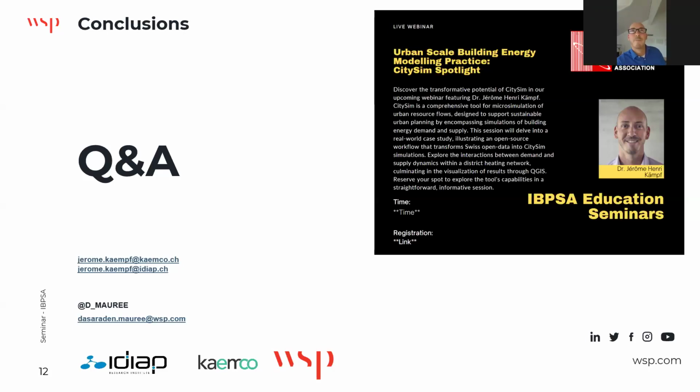Basically, if we have elements in the city that are not buildings, such as covers for parking spaces or bus stops, that you want to fit with PV, you can use what we call the shading surface, so that you don't have any thermal or complex calculation done on these surfaces, and you can fit those surfaces with PV. But the PV results won't be associated with any building, so of course it cannot cover the consumption of a specific building.